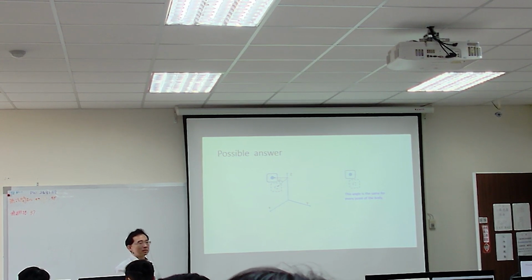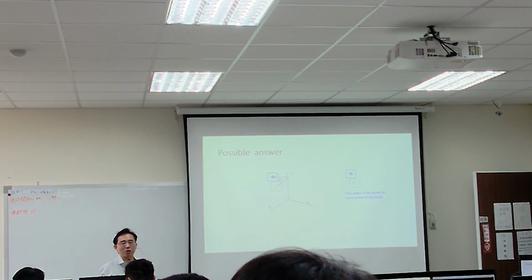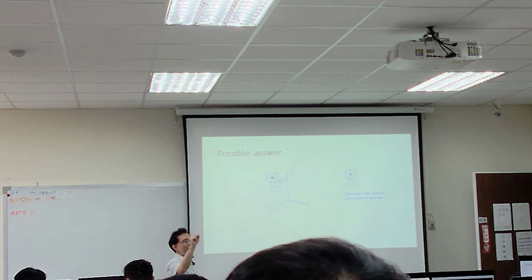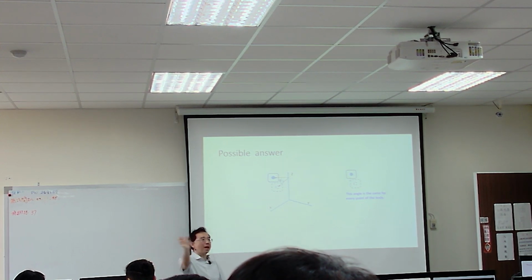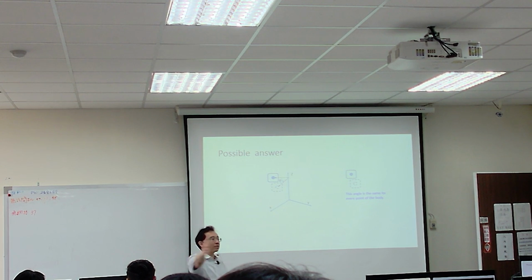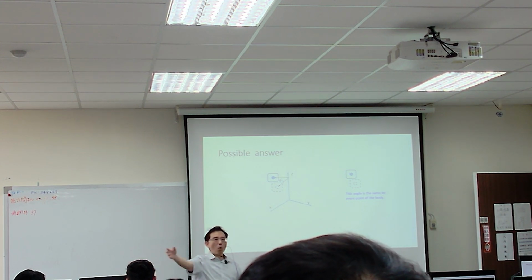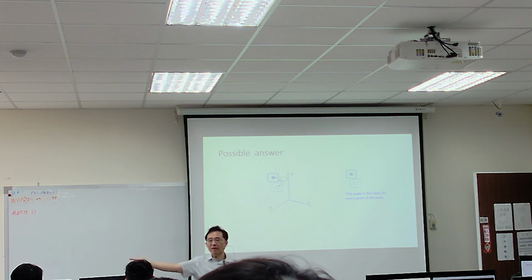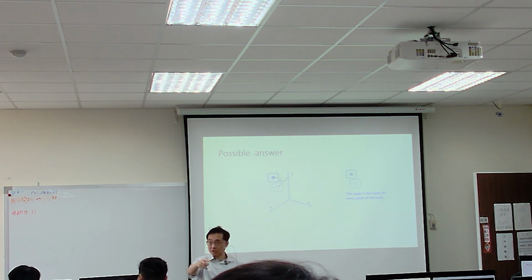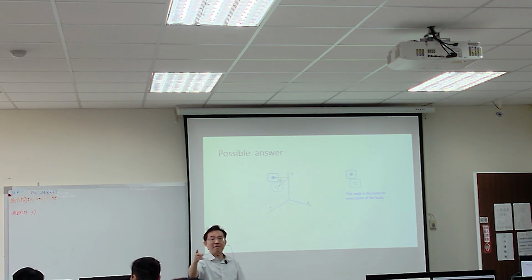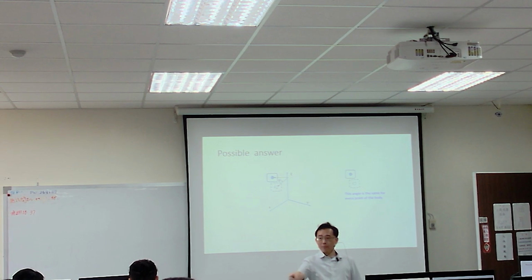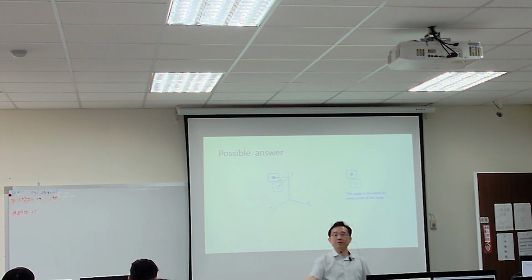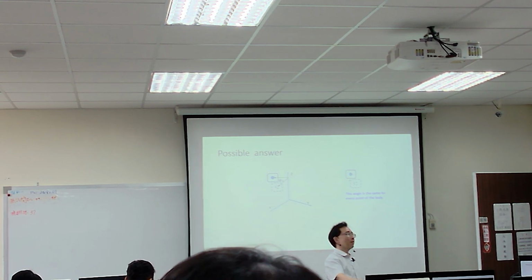Sometimes we need this information. For example, this is my end-effector. Of course, I have the angular velocity for the end-effector. But what about the finger velocity? Can you describe it as angular velocity? Yes. But what if I need not only angular velocity? For example, if I want to touch this screen with proper velocity, I'm looking for the linear velocity.